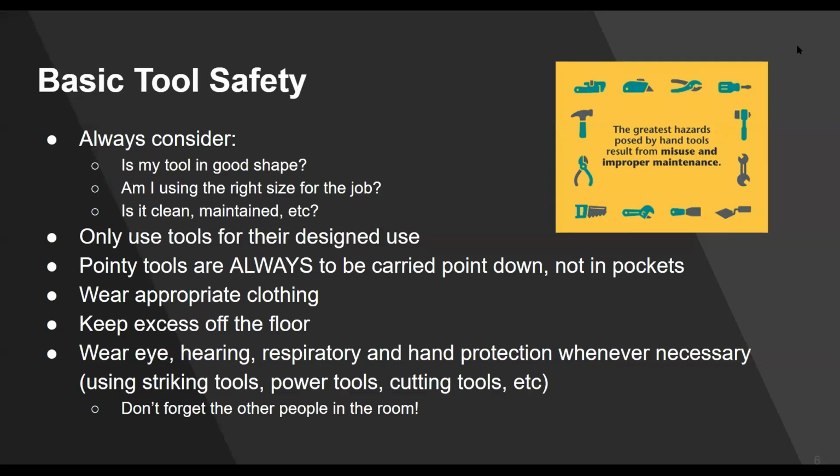So make sure that your tools, of course, are unplugged, especially if it's a power tool. Make sure that they're staying clean. Make sure that they're not slippery, especially if you're using grease at any point. I've seen it happen where someone had a drill bit that had too much grease on it and it slipped right off of a piece of aluminum and went through his finger. So be careful of those things. They're very, very dangerous if they're not used in the correct manner.